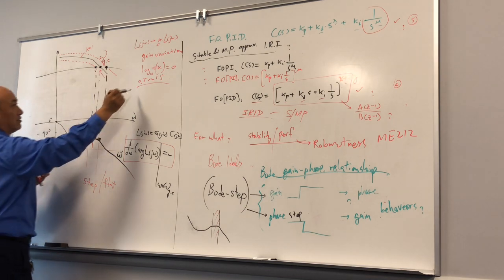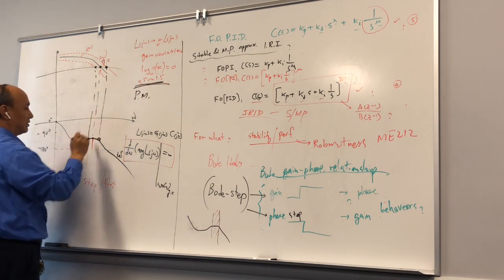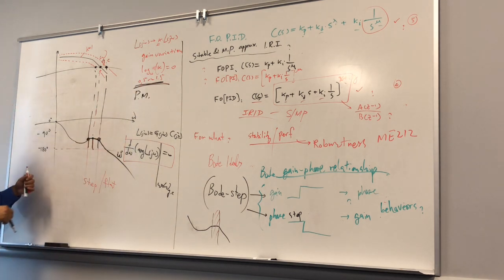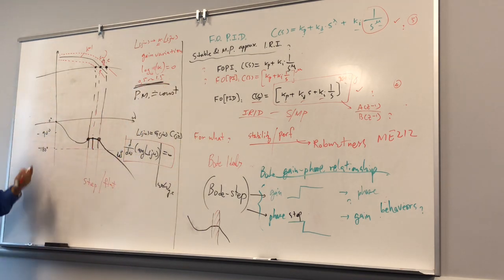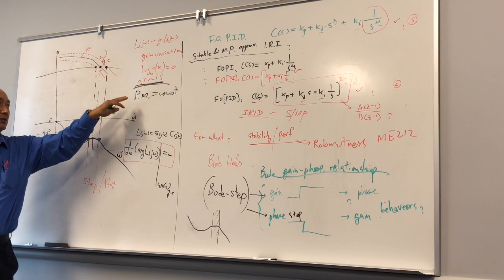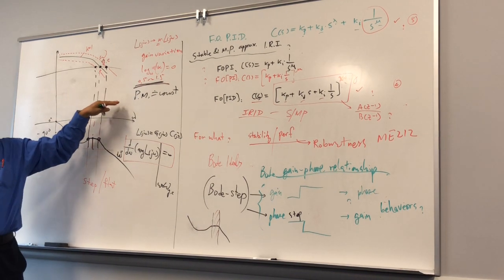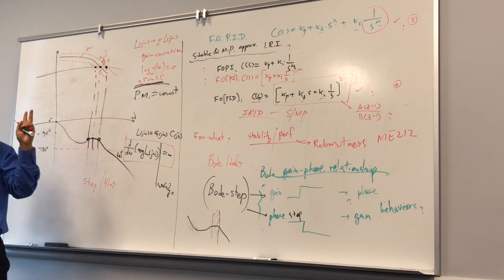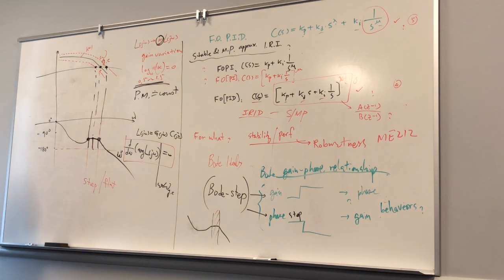So in this range, your phase margin is all this way, okay? It's almost constant. It didn't change. Therefore, I say my system transient behavior is linked to phase margin. So my performance stability margin is almost independent of your gain variations here. Isn't this robustness? Yes.